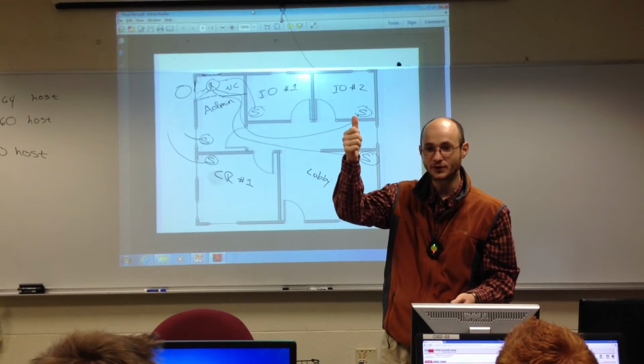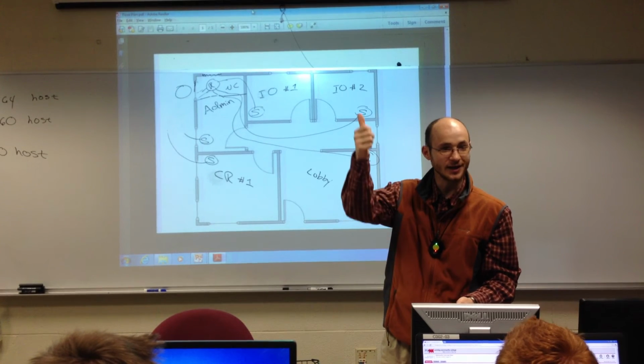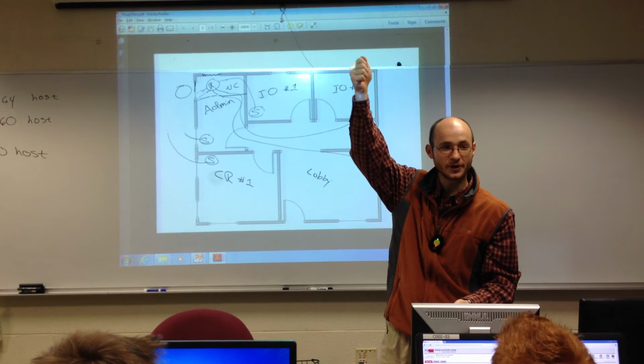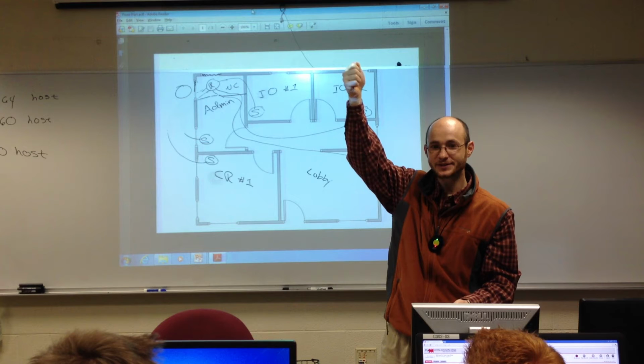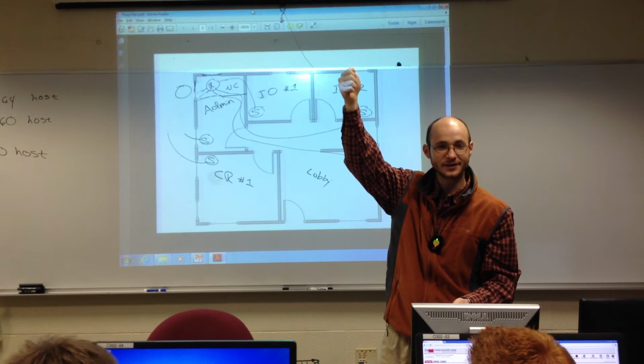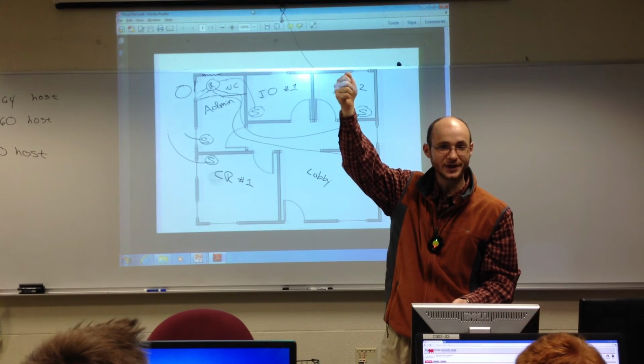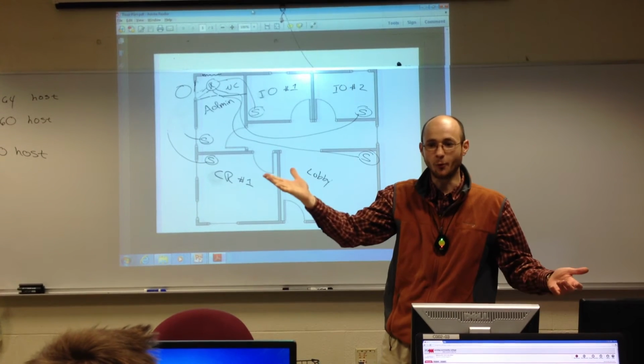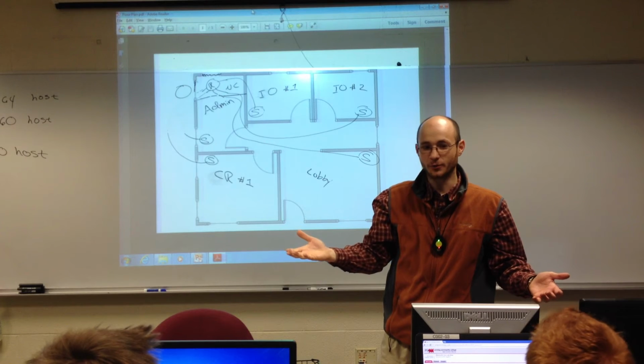Now you guys know this to be true if you just take a straw, put it in your soda, and cap the one end with your thumb and pick up the straw. What happens to the liquid? Stays in there, right? And that's what would happen to your toilet if you guys tried flushing it and you didn't have a vent. What's in that vent? Nothing but airways.